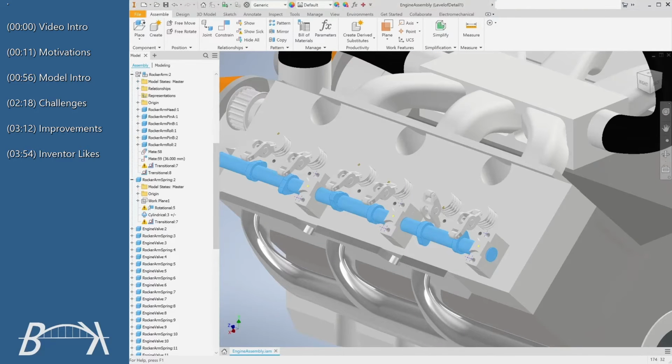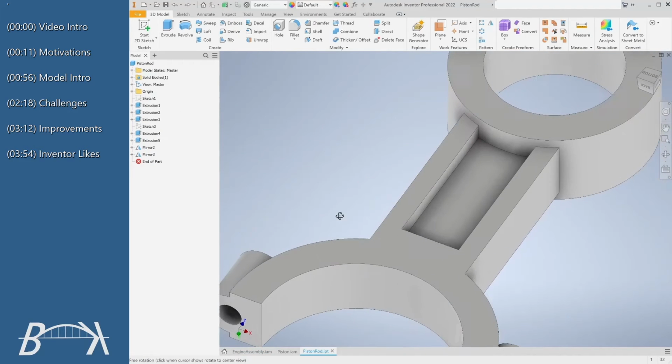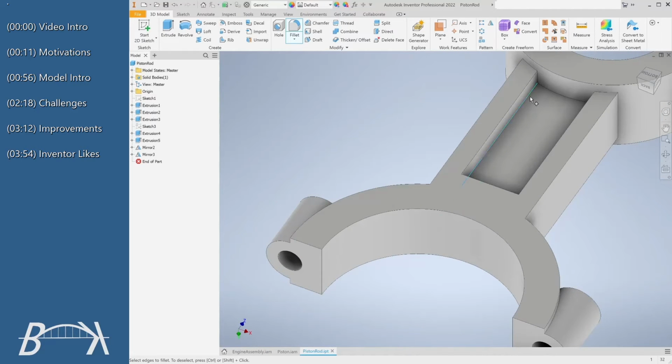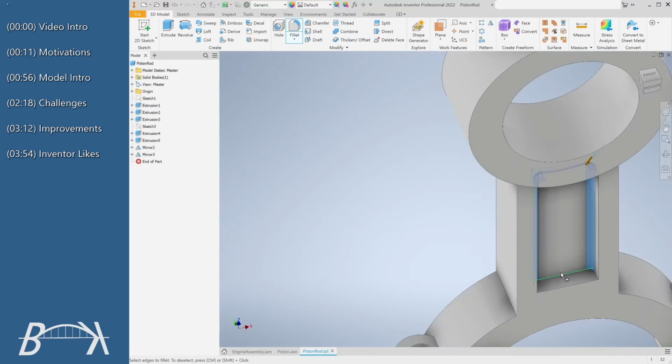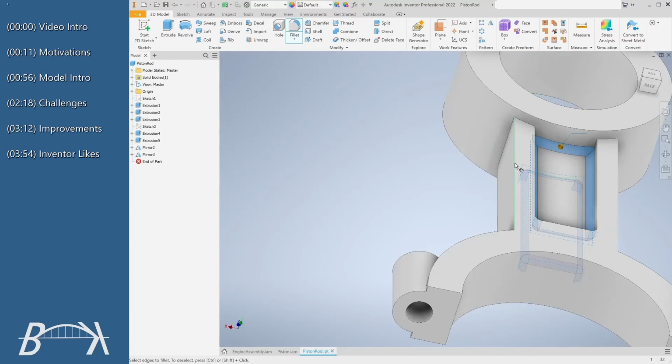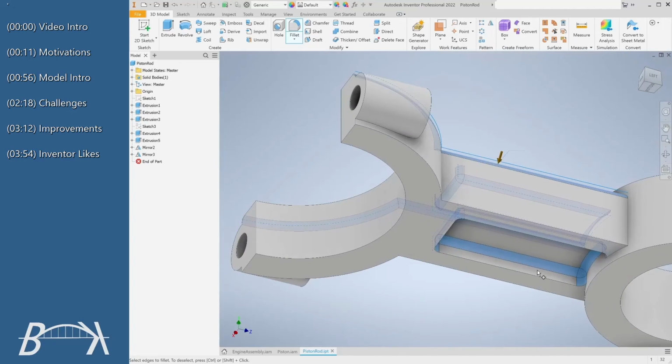Anticipating issues with how my system might handle all of these constraints, I held off on applying fillets to a lot of edges that should use them, which is the perfect transition to the next topic. Project improvements. I would have filleted items ahead of time. Waiting until after constraints were set was a mistake, because constraints are looking for surfaces and axes that are redefined when I end up adding fillets.